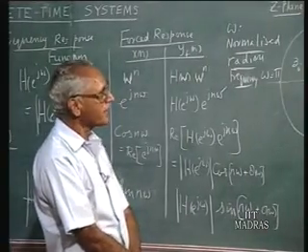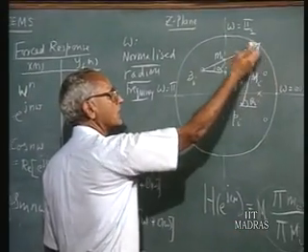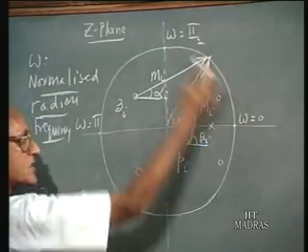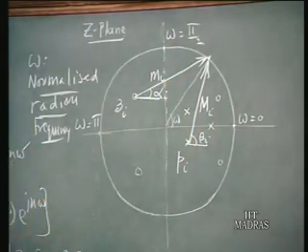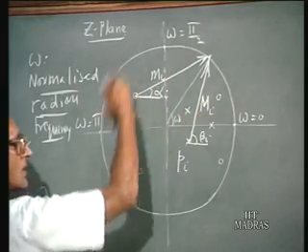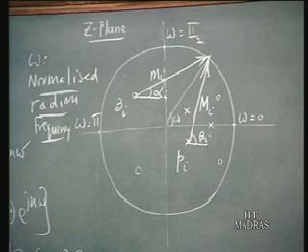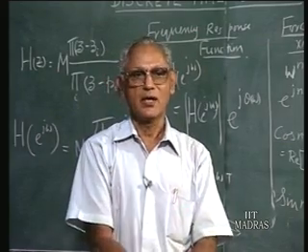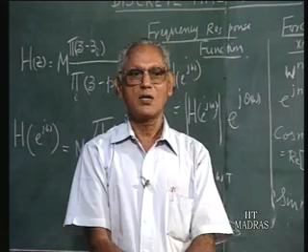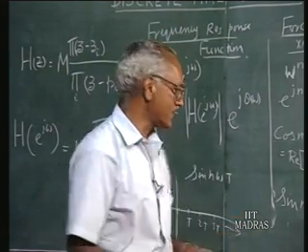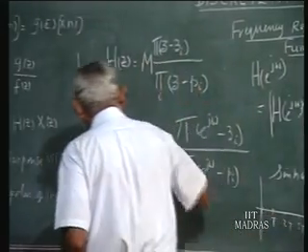What we observe here therefore is, as you change the frequency, you can calculate the frequency response. You can go up to pi, 2 pi and so on. Suppose you come back to 2 pi and start all over again, you must get the same frequency response, because as you move along this unit circle, complete one circle and come back to the same point, you must have the same frequency response. That means as omega increments by 2 pi radians, whatever frequency response we had in the original value will continue to be the same at the new value, which means in other words that the frequency response function of a discrete time system is periodic in character. So let me illustrate that